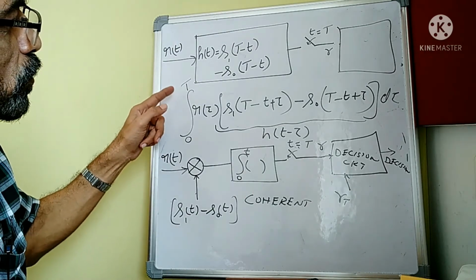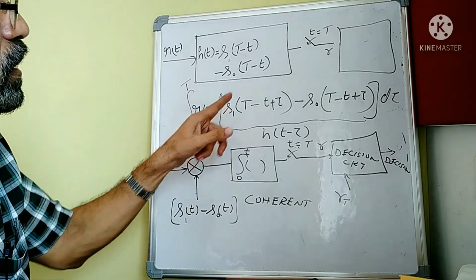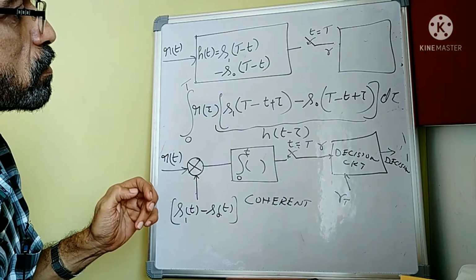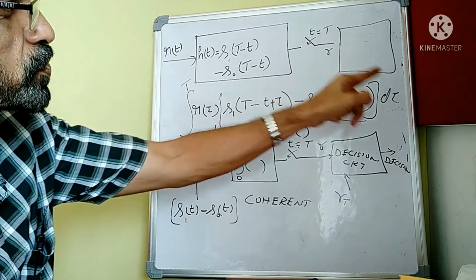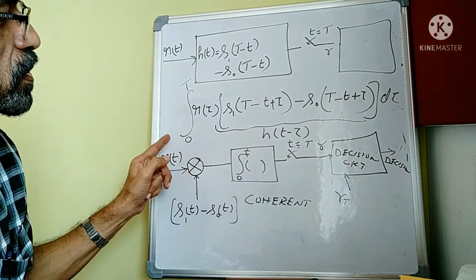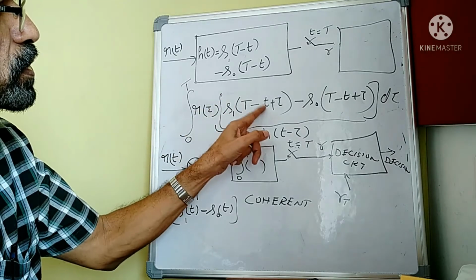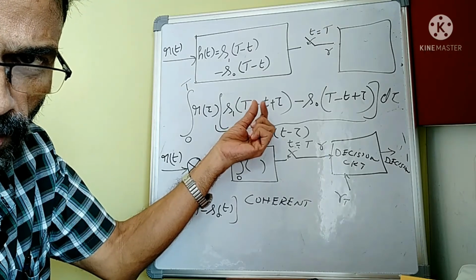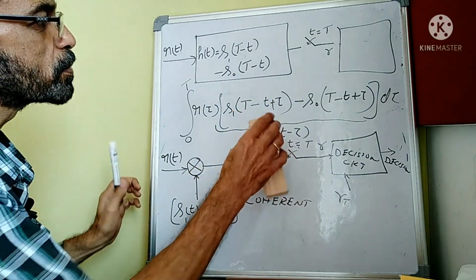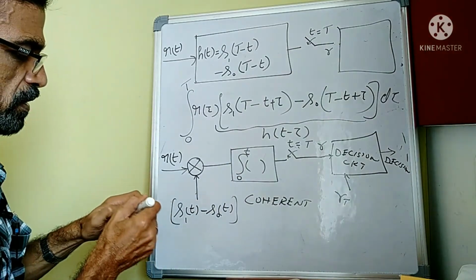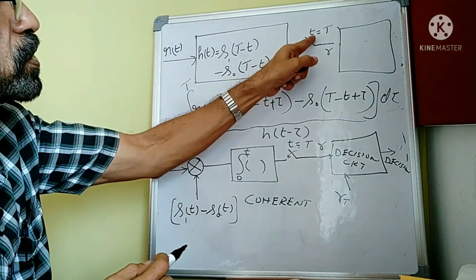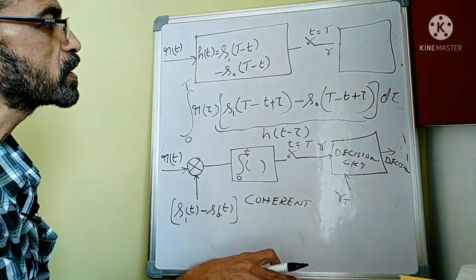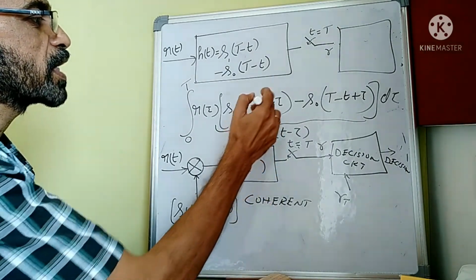And you are integrating it at the end of the integration interval, that is, you sample at t equal to capital T, not at the end of the integration interval. I apologize for that slip of the tongue. You sample this result at small t equal to capital T. When you set t as equal to capital T, exactly the sample you get will be this.